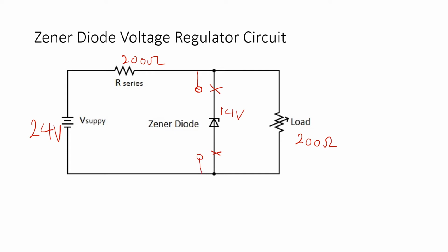So this will be gone, and this is what we have. Now, if we do this physically in the lab, we take a multimeter and we measure across here, voltmeter, on volts. If we measure here and we get greater than 14 volts, we know it will regulate. If it's less than 14 volts, it will not regulate. We can measure it easily, but how do we do the calculation?